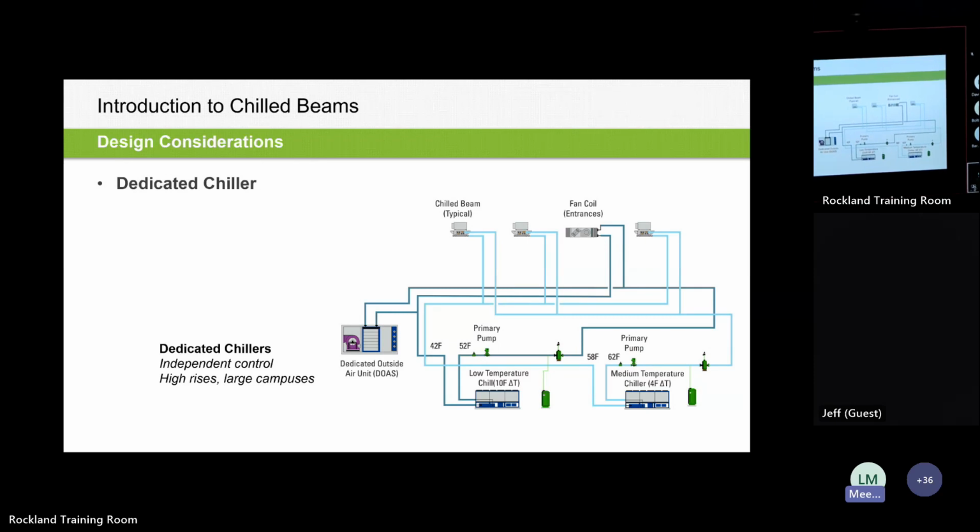Setback. You wouldn't turn the system completely off. It might be off for a time while the building is within the set point or the setback set point. But if it goes below it, the system will come back on.